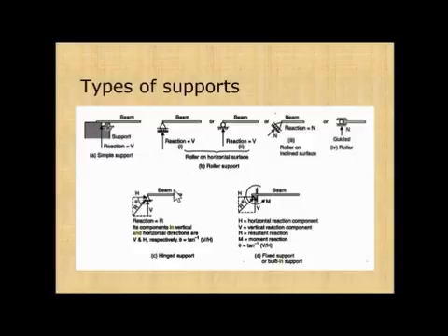Now the main thing is not analyzing this diagram, the main thing is to draw the FBD for these types of diagrams. In this case, if you want to draw the forces, then this V will be upwards, that is a vertical force, the horizontal force will be perpendicular to this, and as a result we will get the resultant force. The most important thing in this case is drawing the resultant force and showing all the reactions and net forces acting on this diagram. That means we have to be clear about the free body diagram before coming into these types of problems.